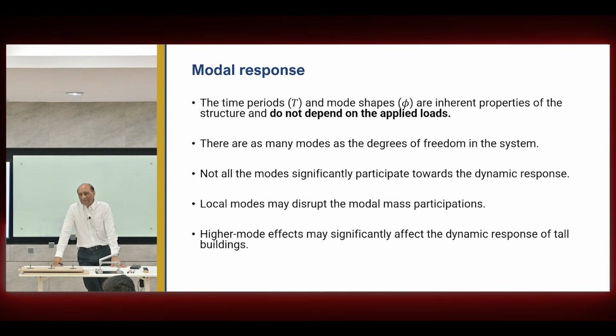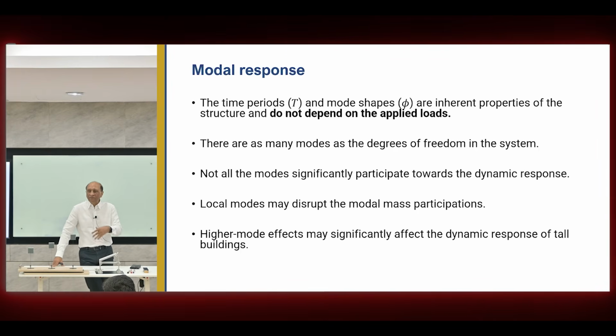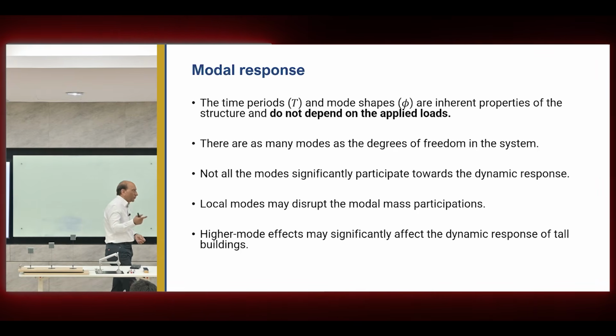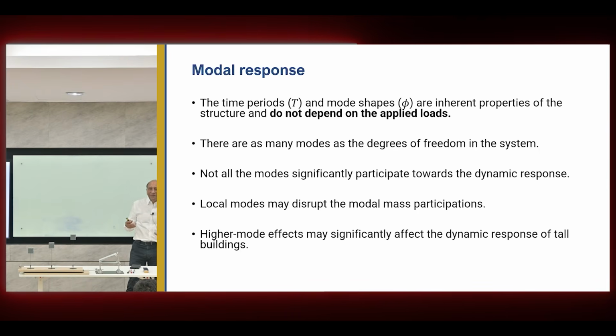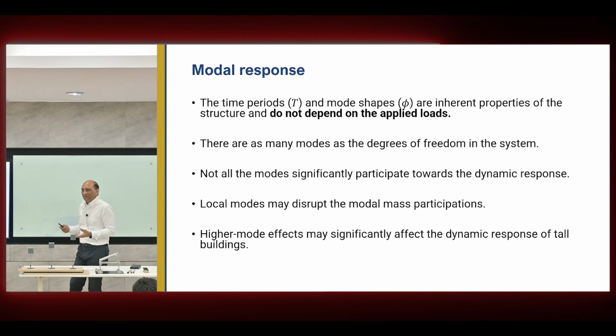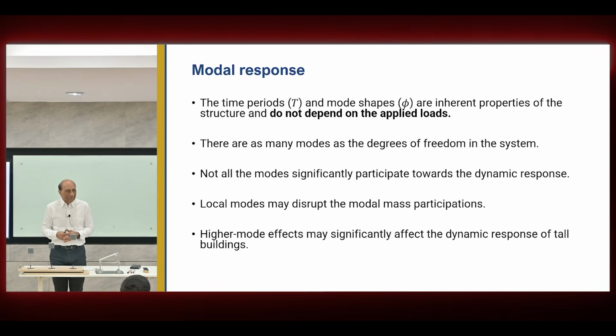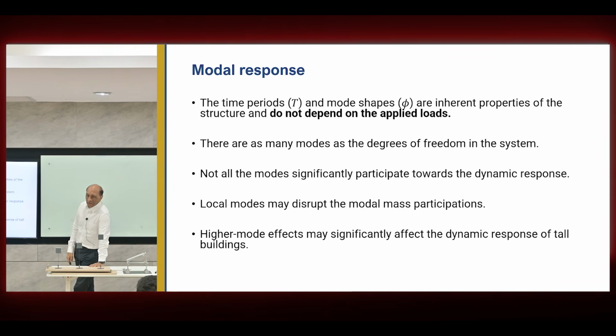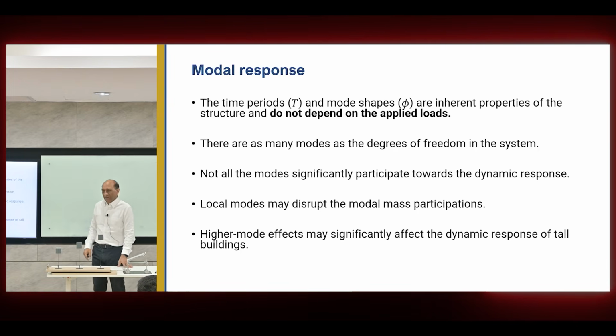So please remember and understand these basic concepts of degrees of freedom of a point, degree of freedom of a frame member, degree of freedom of a structure, of a building. They are different. So when you're doing the modal analysis, you should look for at least 10-story building. You should look for 30 numbers, because 30, I showed you just now 3, but it can be as many as the number of floors. We normally don't look for all of them, and I will tell you later.